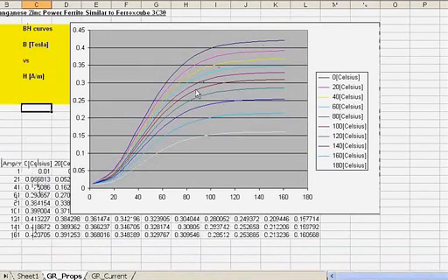So I can show the resulting family of curves here. These are generated by the hyperbolic tangent functions. When I write a program to solve problems in QuickField, I also make the same program generate an archive, a file of the properties that were actually used to run the model, so that if there's ever a problem, we can come back to that and check that the properties were correct.